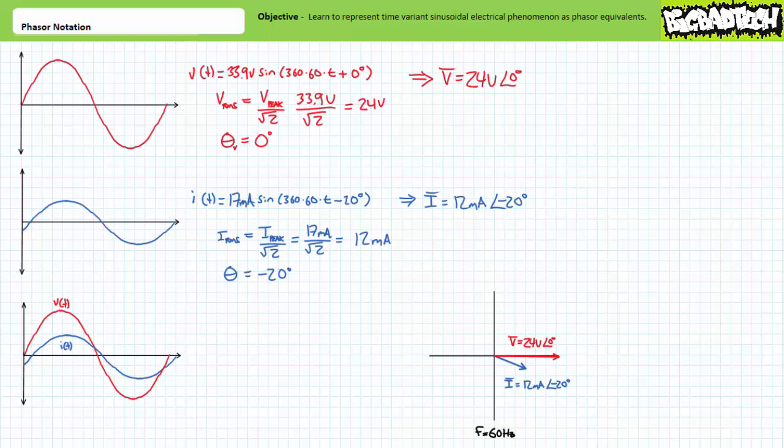Phasor notation strips down a heavy sine wave into only its most essential properties, the effective value and the phase shift, essentially the magnitude and direction of a complex number expressed using polar format. It should be noted that frequency is still with us, and that this phasor diagram is only relevant at our current given frequency of 60 Hz, the simplicity being that both voltage and current are assumed to have the same frequency. Phasor notation, in addition to compactly representing important electrical properties, is also a means of illustrating a plot of these properties in as small a space as possible.